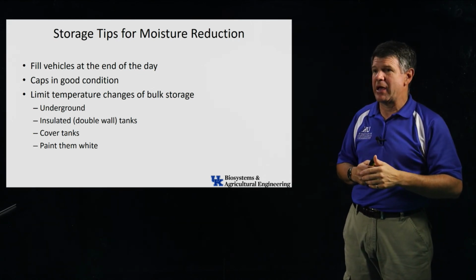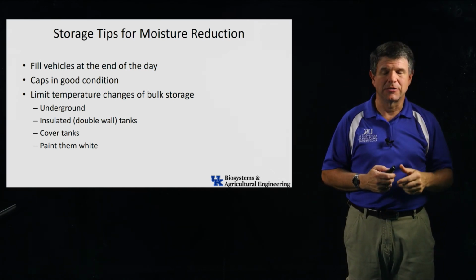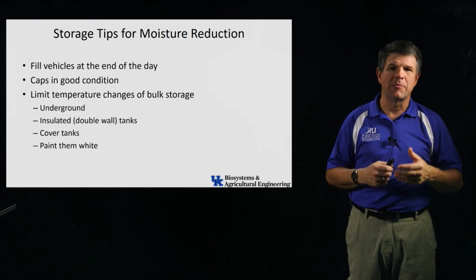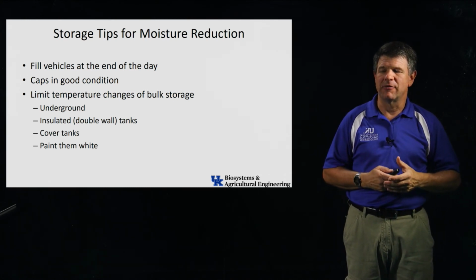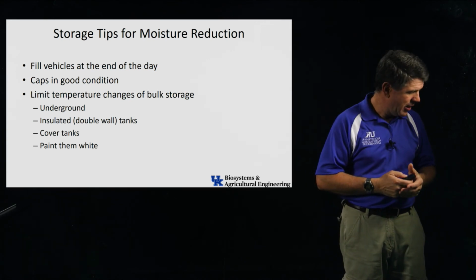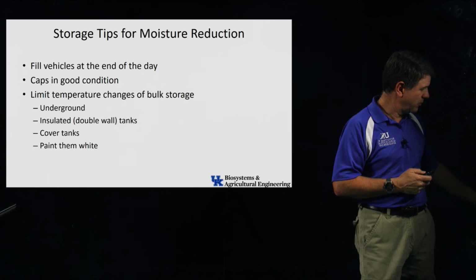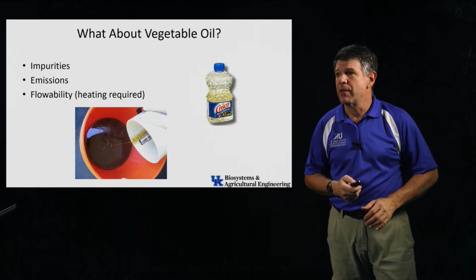So underground is best. There are a lot of environmental implications and storage regulations, so that's usually not very practical to do, but you can cover them, insulate them, or paint them white so that the solar radiation doesn't have much effect on them. Those are all things that can help you with how you're going to store your fuels and so forth.